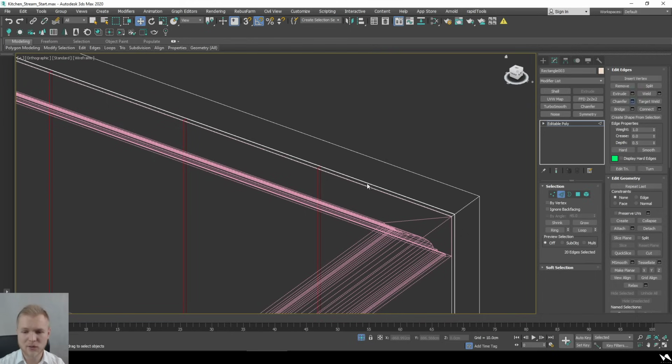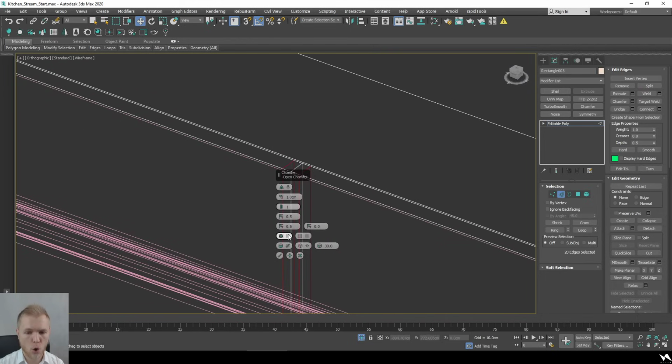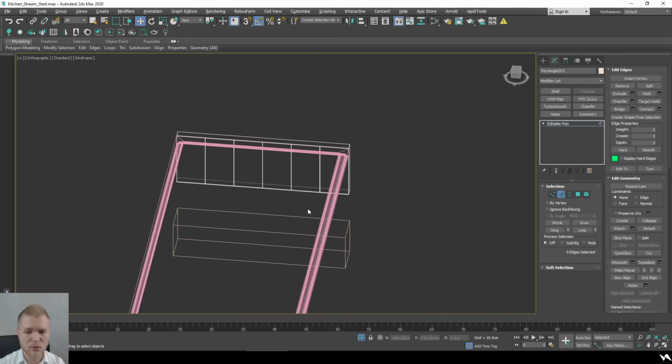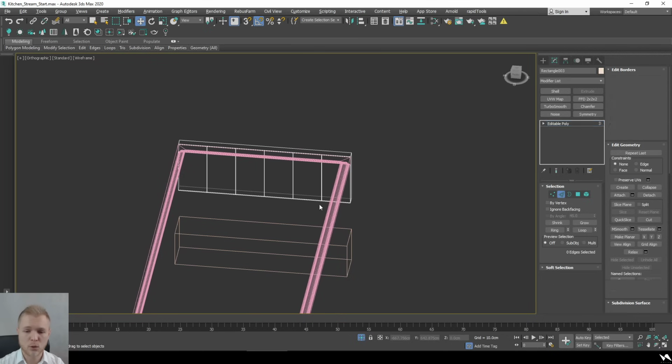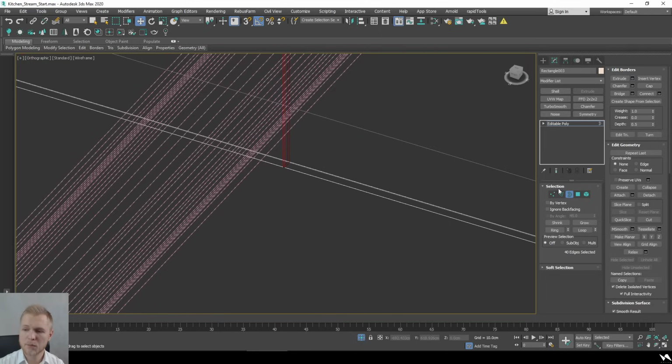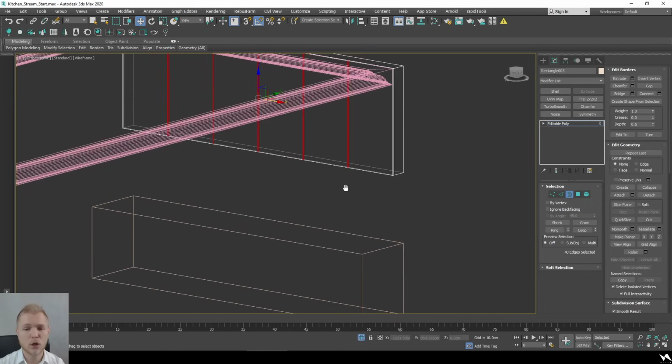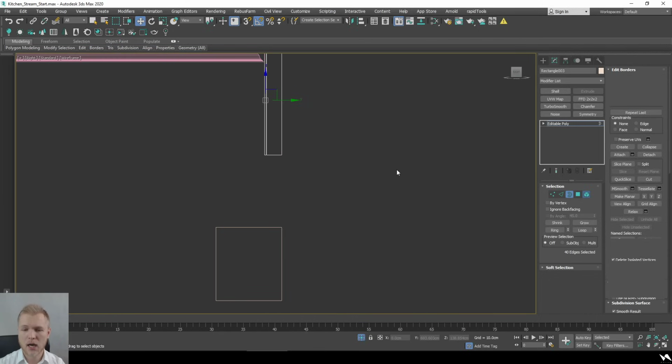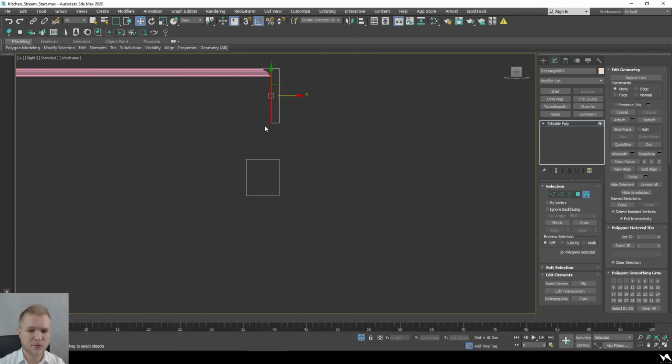So what we can do is simply use Chamfer, open this Chamfer, and make sure that it's roughly about 2 millimeters. As always, you don't have to be precise. Press 3 to go to the Border. Now all the borders, so open splines, open polygons, are going to be selected. By selecting this border, we're able to use Cap. That is going to close those gaps and will allow us to basically start working with those objects as fronts.